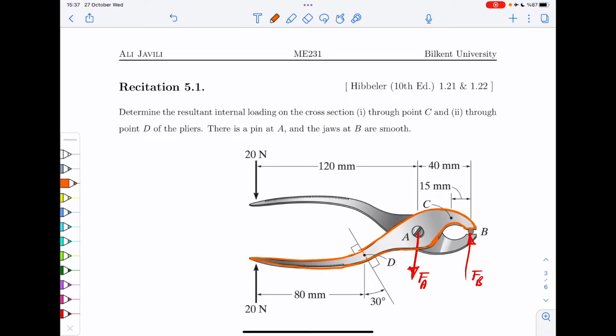So we are going to analyze this. Now, what you want to do is first to calculate the internal forces and moments at point C. In order to do that, we are going to just basically cut the structure here. And then when you cut it there, either you cut it from right or left. Obviously from right, it's simpler, it's shorter. So we are going to cut it from right, and then we write the equilibrium for this red piece that I just drew here. Okay, so that piece, if I can replicate it, it's going to look like this, for instance.